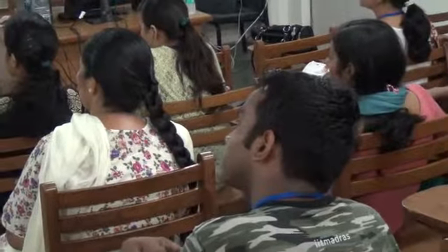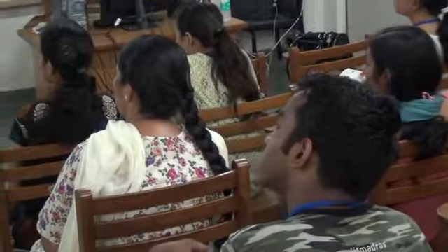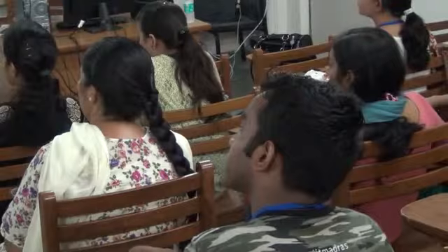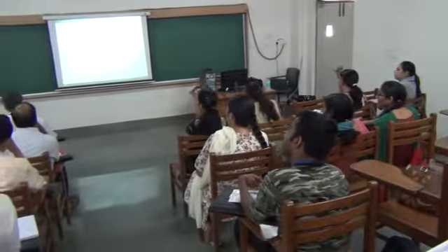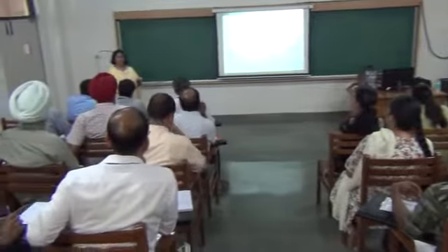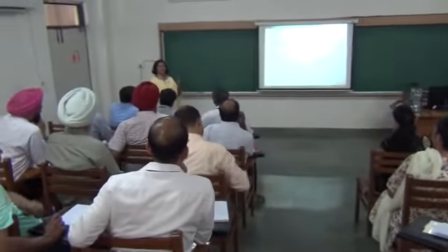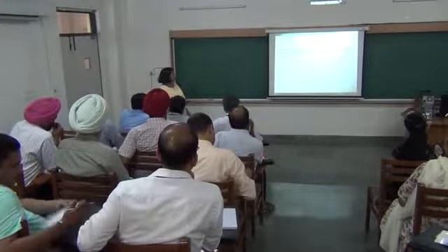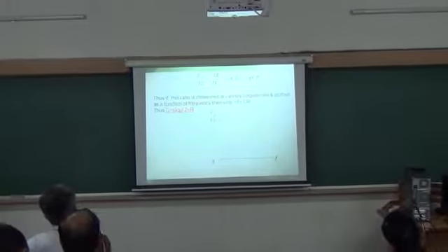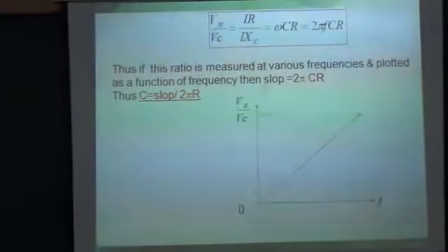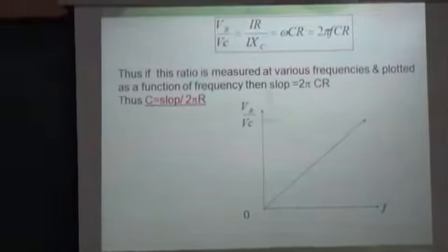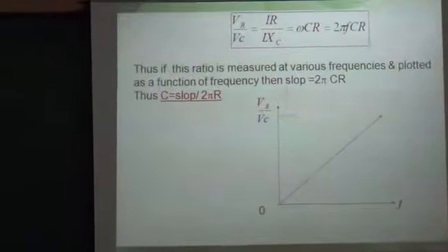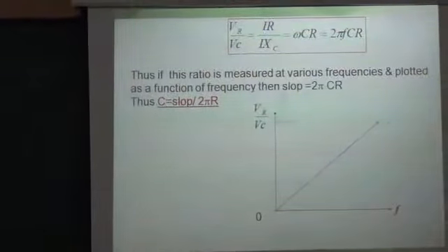And given a capacitor, you take it 0.0. I'm giving you a capacitor. After that, what should I do? Practical problem. I'm talking about practically, not theoretically. Theoretically, you should take readings: VC by VR is 2 pi FCR. So from 0 to infinity, I can take readings. No problem. But when I am going to do it practically, what precaution should I take so that afterwards I should not have to tell the student to take a particular range?